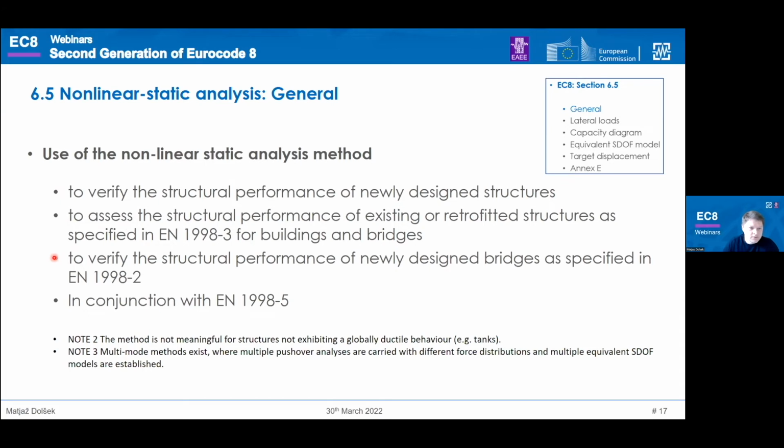And also to verify the structural performance of newly designed bridges, which is also new. We also have to account for soil-structure interaction as specified in Eurocode 8.5. It is not prescribed that nonlinear static analysis is used, for example, for tanks in Eurocode 8.4.